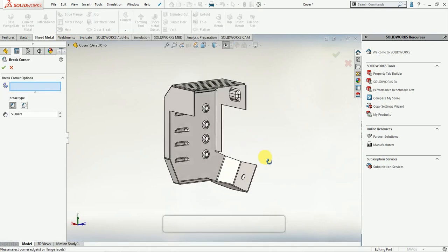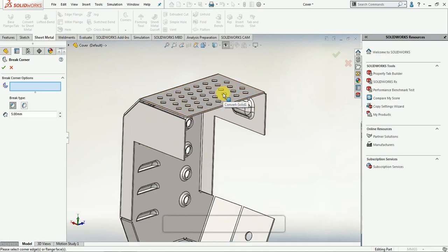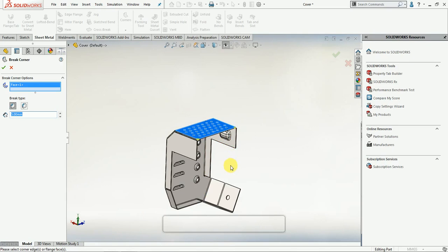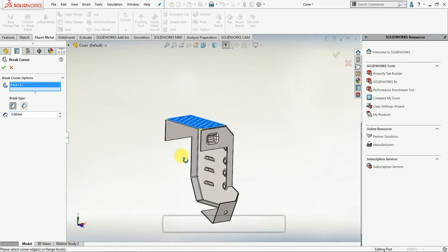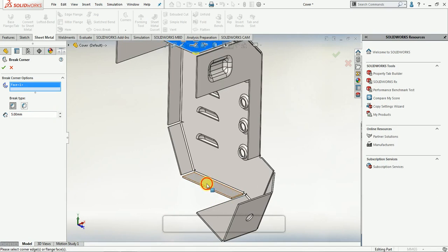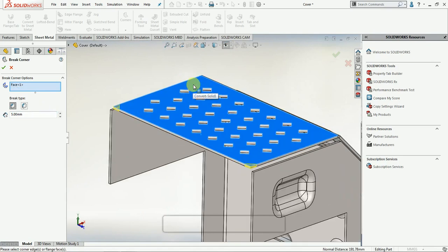So the corner treatments, such as the bends, I can create and control easily through different kinds of corners. For example, I am using the break corner options to control my edges through a fillet as well as chamfers, and those properties can also be easily controlled through numerical values, which are nothing but my dimensions.